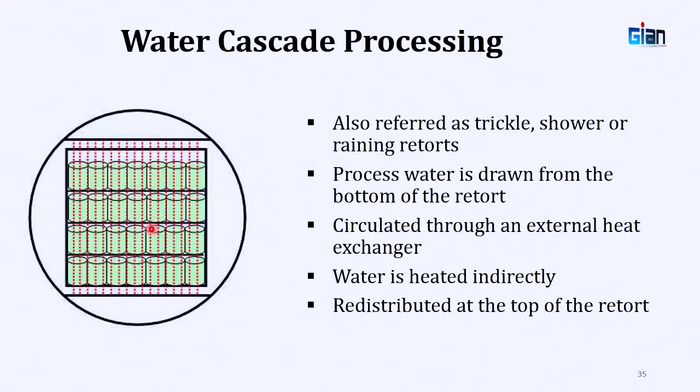So in that one pass, this can may come down from 120 to 110, but here, because the cold water temperature is probably 50 degrees, it will not come down from 120 to 110 in one pass. Maybe it will come down from 120 to 115, right? So the cooling is slower here. So heating is faster here and slower here. So cooling is also faster here and slower here.